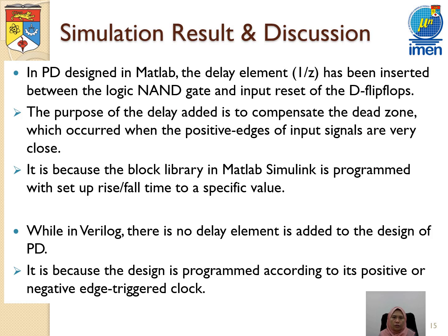And for the simulation result in the PFD, we tried to design our architecture using MATLAB and also Verilog, and we compared the performance, and we found out that in MATLAB we need to add a delay element in order to compensate for the dead zone.